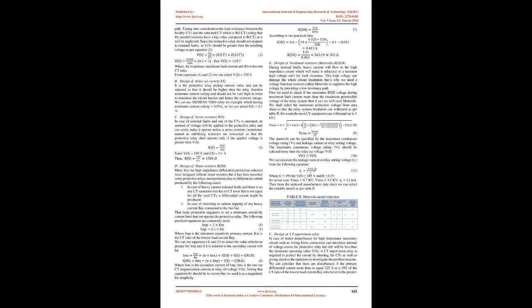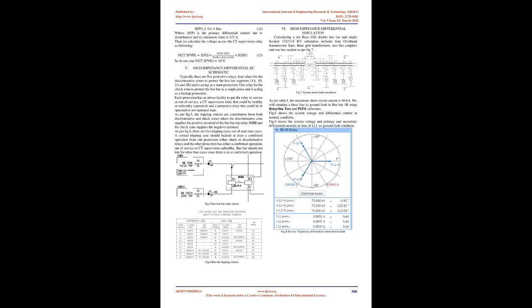C. Design of series resistors R_S. In case of external faults and one of the CTs is saturated, an amount of voltage will be applied to the protective relay and can easily make it operate, unless series resistors, sometimes named stabilizing resistors, are connected, so that the protective relay shall operate only if the applied voltage is greater than V_S.